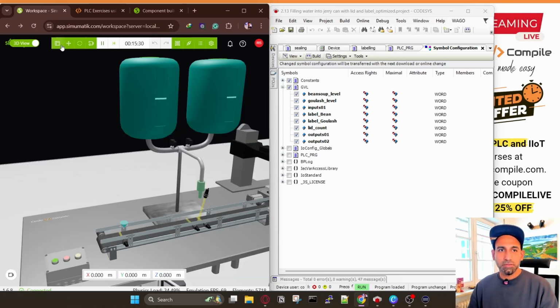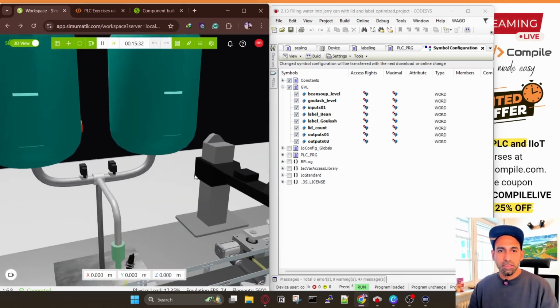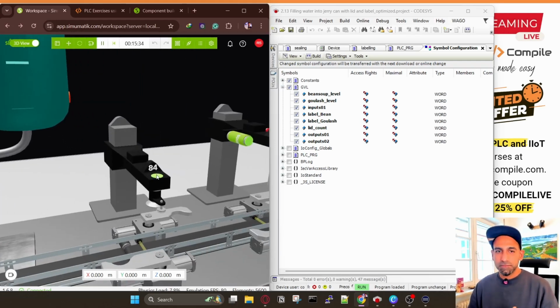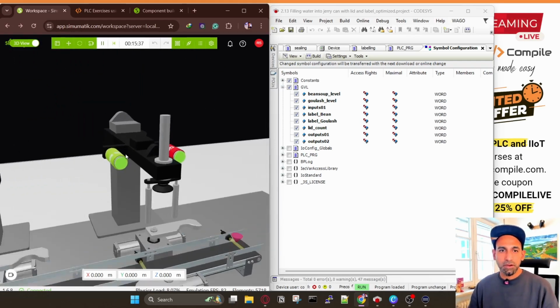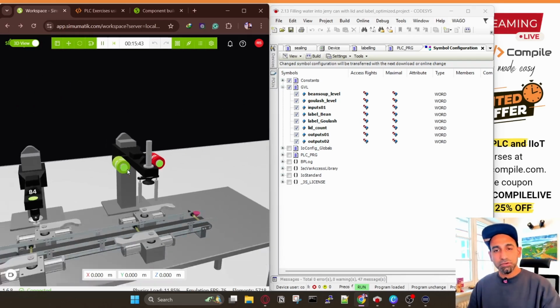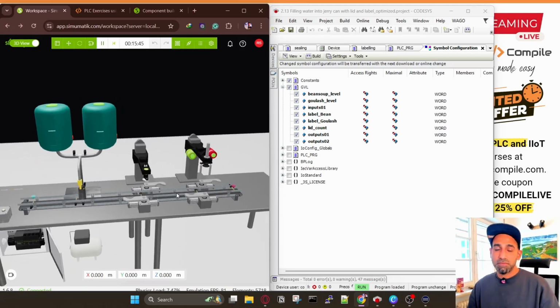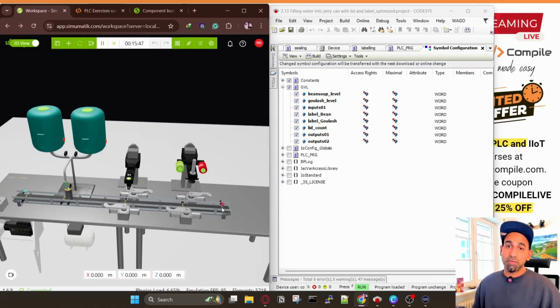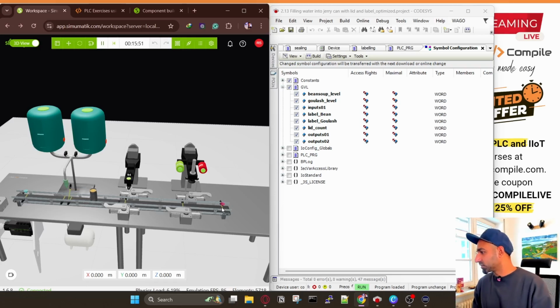So all these variables which you see here, the tank level, the number of lids that are left, or the labels which are going to be empty, I can fill it. Labels which are left, these are analog input values, which are going to the analog output. We don't have analog outputs in this PLC. Maybe in the next units when I'm going to connect, maybe I need it. But right now, we are just working with digital inputs, outputs, and analog inputs.